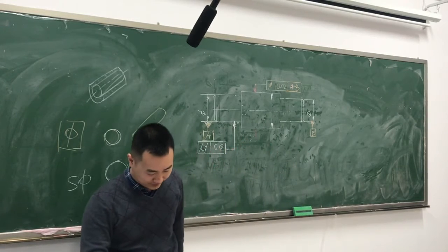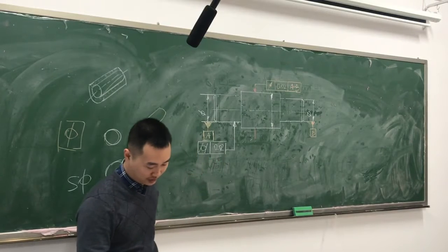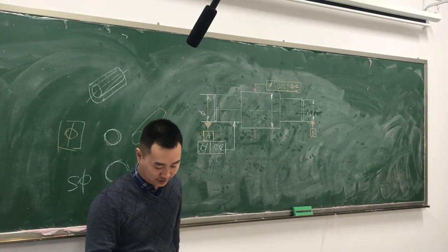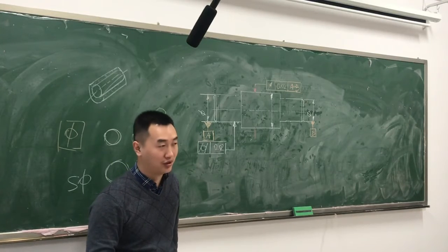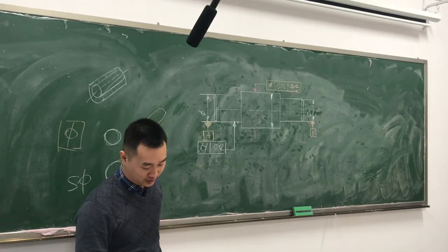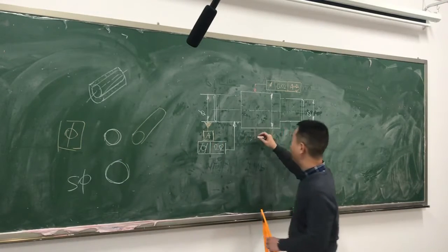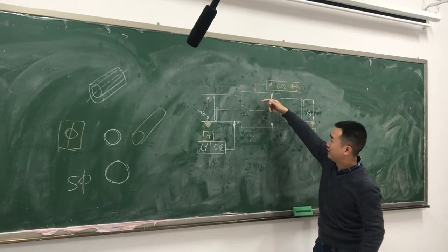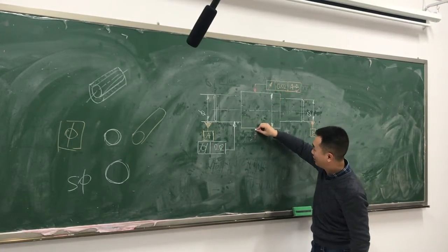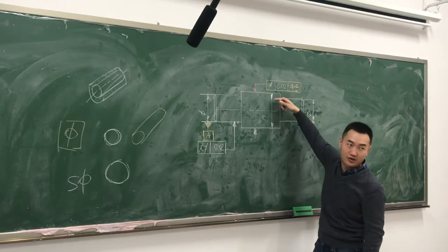Okay. And the last one is the circularity. The circularity is also one kind of form tolerance. Here, it's all correct, but it also has the same problem as the first one. The lead line should not act as the extension of the dimension line.